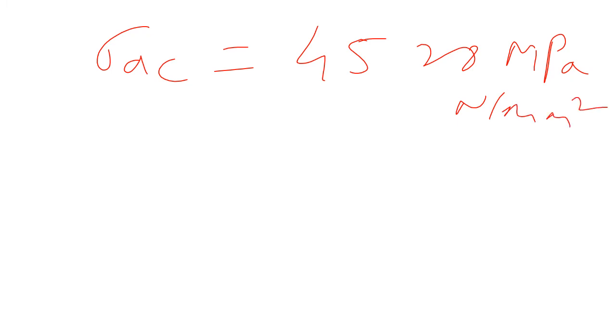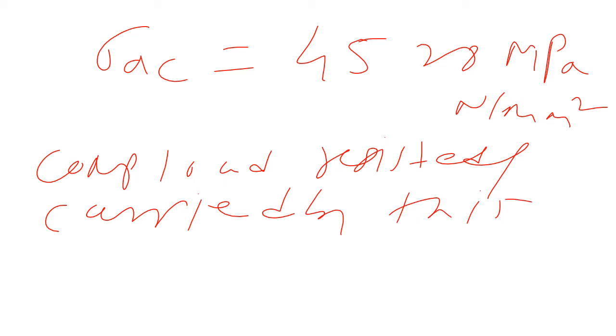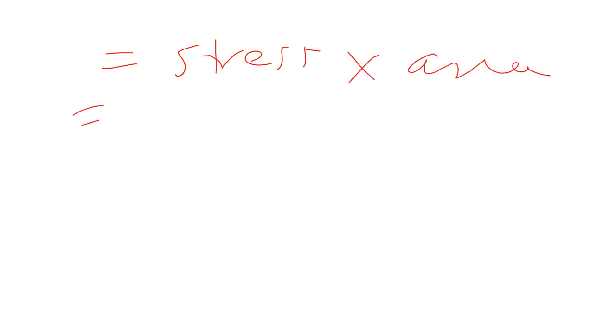So now it will be easy to find out the allowable compressive load resisted, or carried, by this section of the compression member. So what will that be? It will be simple: we already calculated the allowable stress, and then the area, right? Allowable stress is 45.28 megapascal, that is Newton per millimeter square.